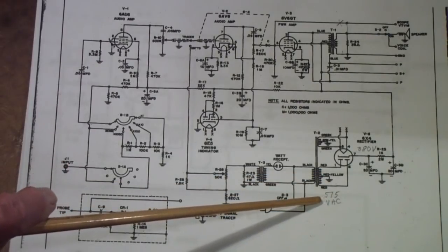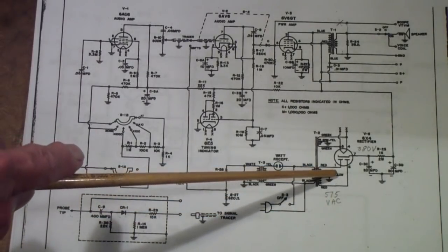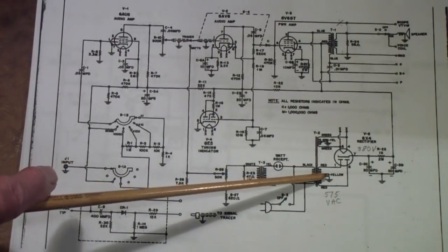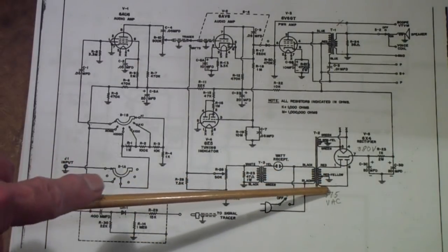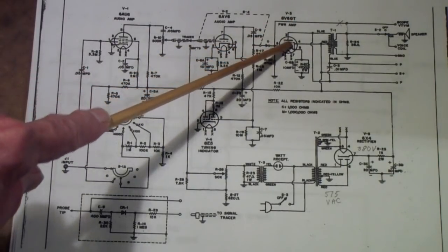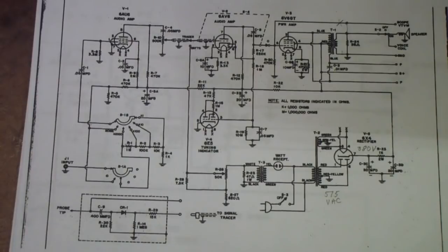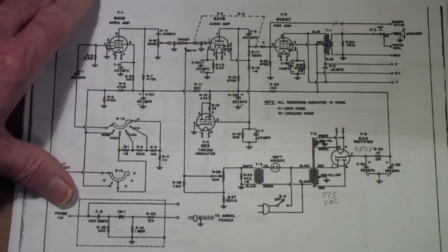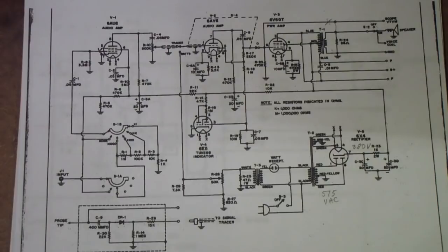In other words, about 280 volts from each side of this transformer, which, by the way, is the rating for the 6V6, and I'm using the 6V6 tube out of this. I admit that while this may seem a little bit kludgy, it is an example, I think, to young engineers that you don't need to go down the high-cost route when you're trying out a concept like this.